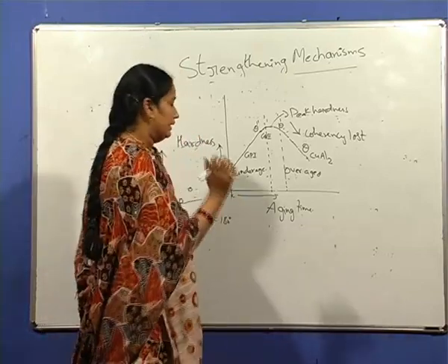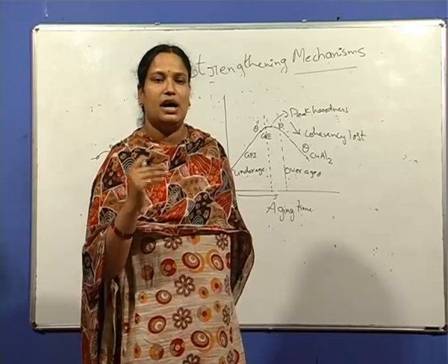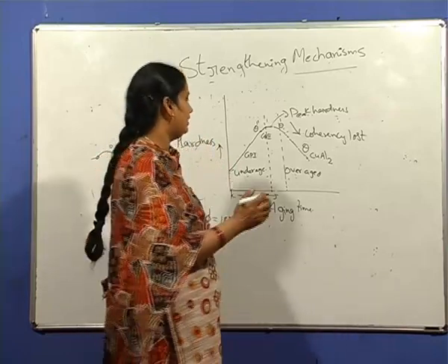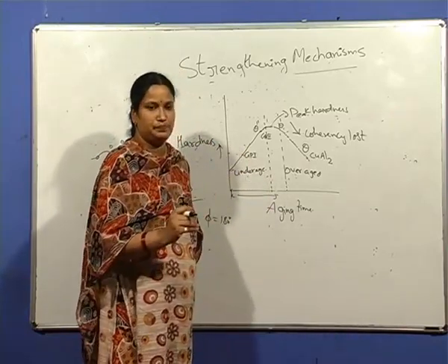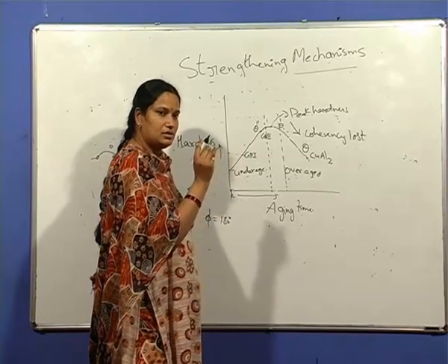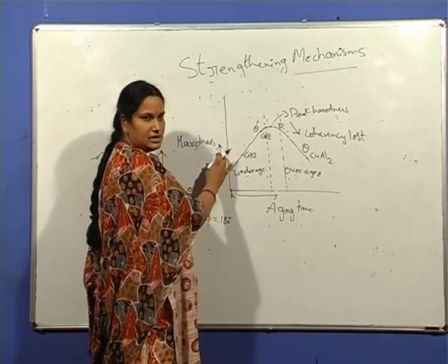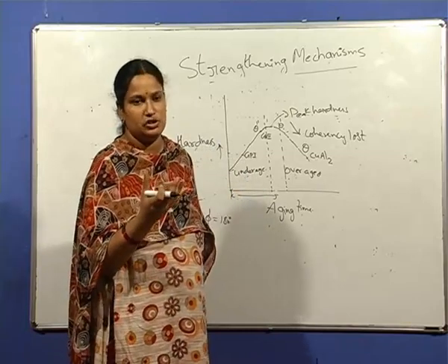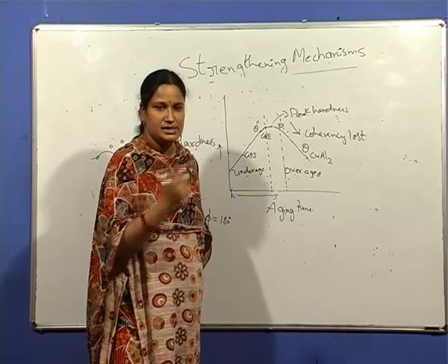So thereby they create strains, lattice strains, and the hardening increases, or the strength of the material increases, hardness increases when compared to the solid solution. Formation of small clusters creates some increase in hardness when compared to the completely solutionized alloy, that is a solid solution alloy. Because of the formation of the cluster, it creates some lattice strains.